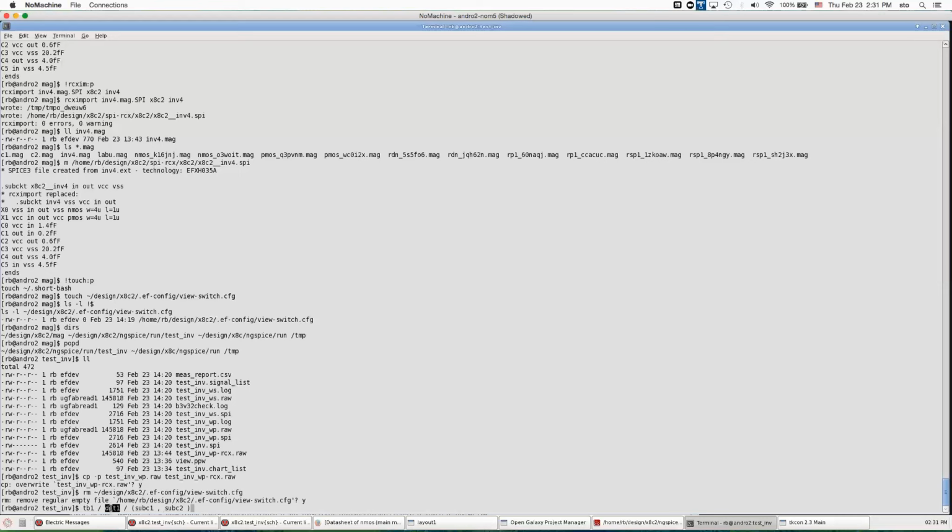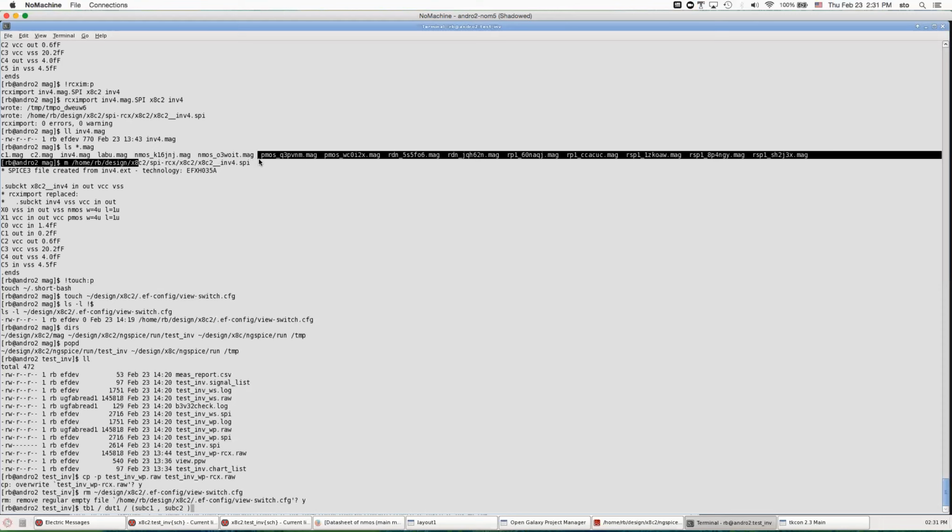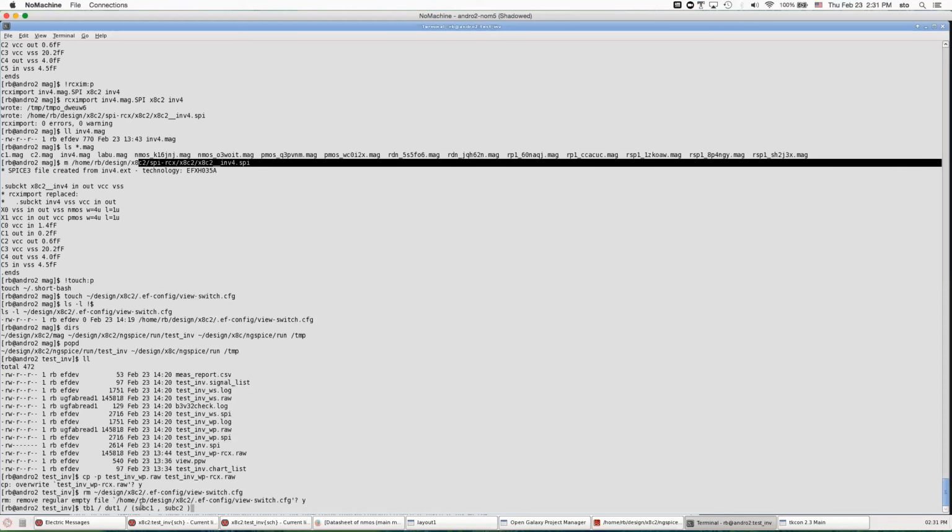But as soon as I generate an RCX view at this level, if I complete the layout for the whole thing and generate an RCX netlist for DUT1, then the older individual RCX netlists for these in the directory structure will no longer be used. Now, there are a number of cases like that where we need more work, we need more testing about whether or not it works.